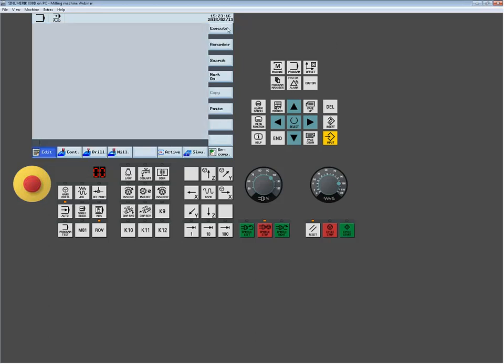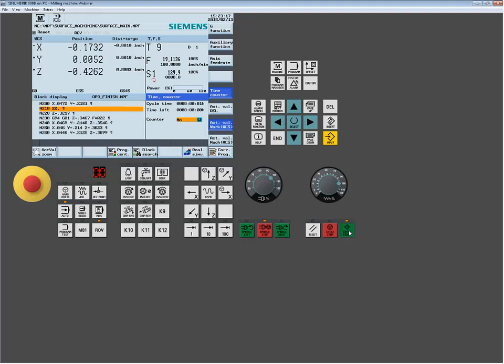So now if I go to execute it, and we start to run it, you're going to see the same kind of results at the machine. And certainly there's going to be a little bit of trial and error. What's the best tolerance that's going to give me my most desirable positioning accuracy and finish? A lot of guys think, put as tight a tolerance as I can. Well, that's not always great.